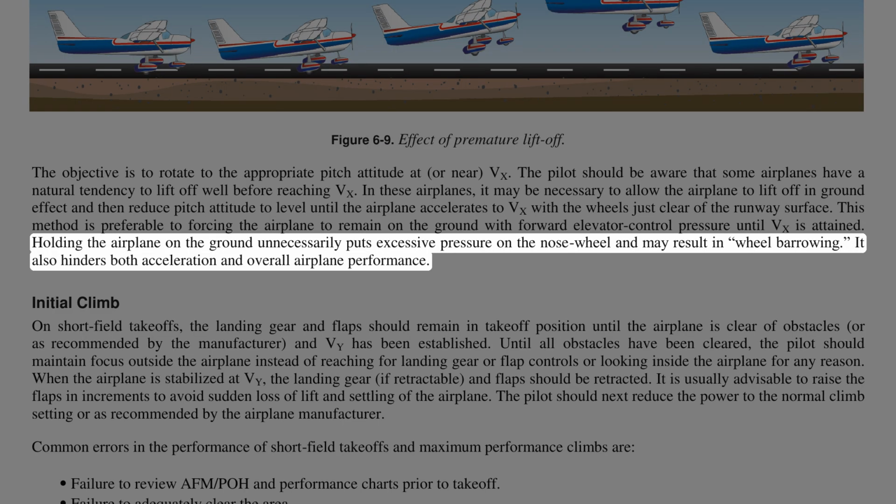Holding the airplane on the ground unnecessarily puts excessive pressure on the nose wheel and may result in wheel barrowing. It also hinders both acceleration and overall airplane performance.